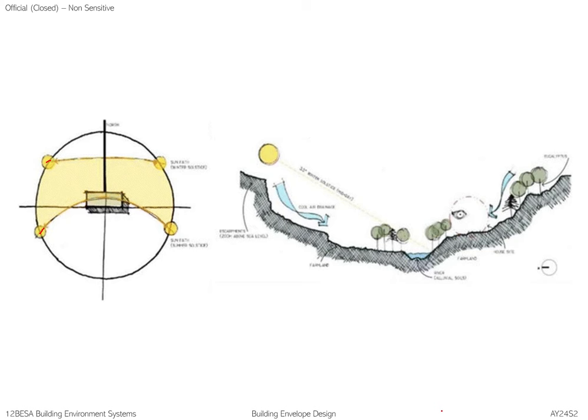So once again, sun path for that particular part. Some of the sketches show that it's somewhat in the valley, but not at the lowest point. So how is it going to affect the wind flow? How is it going to affect the sun path? And yep, sun path diagram. You can see that it is leaning more towards the northern side. So for the southern side, I can open it up. I can use clear glass all the way. I don't even need to use sunshades. It's okay.